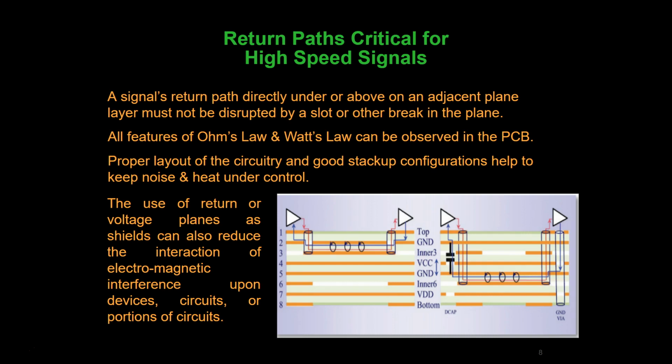So, back to this. Secondly, due to the skin effect, high frequency currents cannot penetrate a conductor, and therefore at high frequency, all currents in the conductors are surface current. And this effect in the PCB will occur at all frequencies above 30 megahertz for a 1 ounce copper layer. Therefore, a plane in a PCB is really two conductors, not one conductor. There will be a current on the top surface of the plane, and there will be a different current or no current at all on the bottom surface of the plane due to the skin effect.